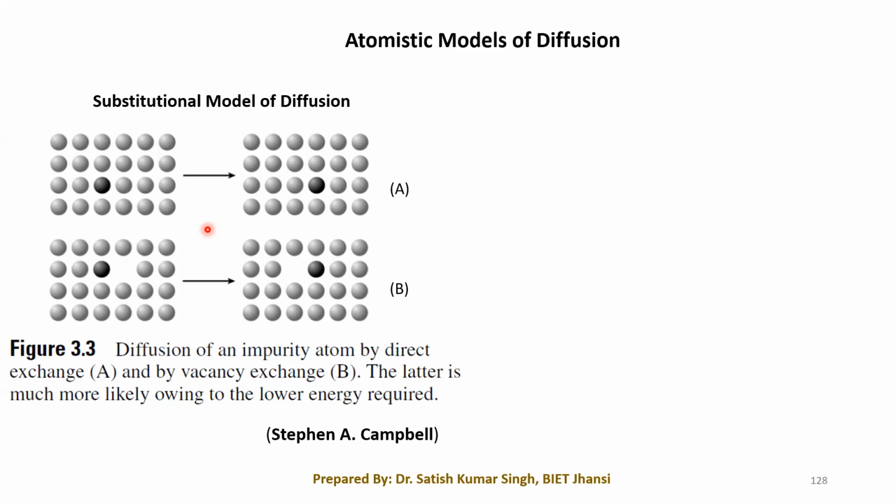Fine. So whenever we have a large number of vacant sites, it depends on what kind of impurity we are adding. Please remember this, because we have a large number of different p-type dopants and n-type dopants. So it depends on what kind of dopant we are going to add. When that dopant diffuses, it may go to the substitutional site, the vacant site, and it will occupy that particular site.